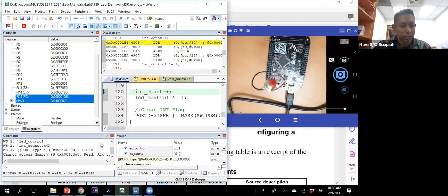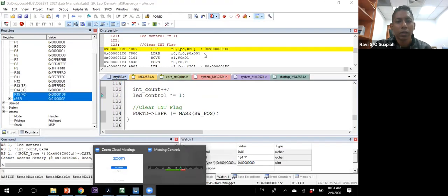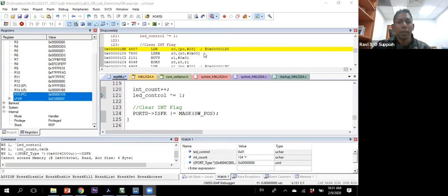You will see that the value jumps a lot. From 65, it suddenly jumps to 100 and so on. It keeps jumping a lot, and at the same time, the LED control also doesn't toggle as expected. The reason I think all of you should know, correct? Yes, debouncing. It's basically the mechanical debouncing issue that causes multiple triggers to be captured.